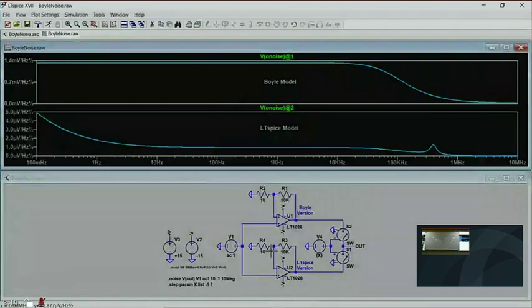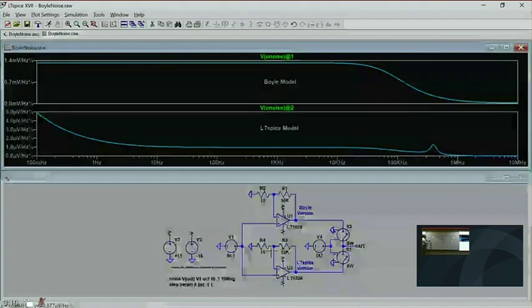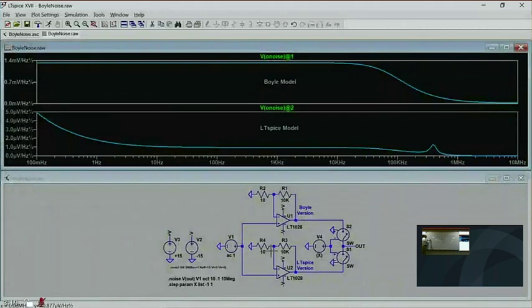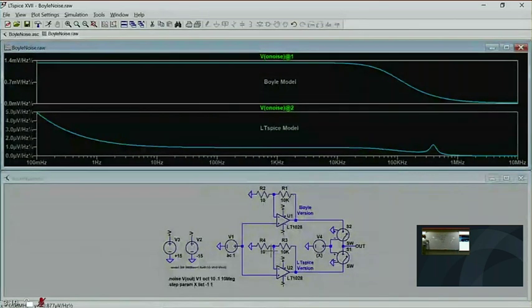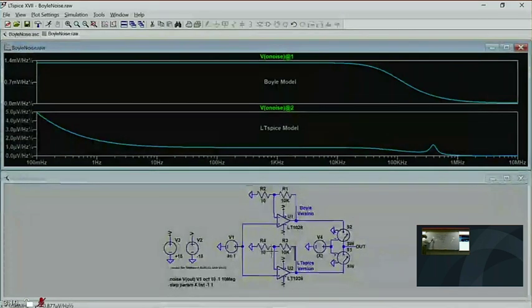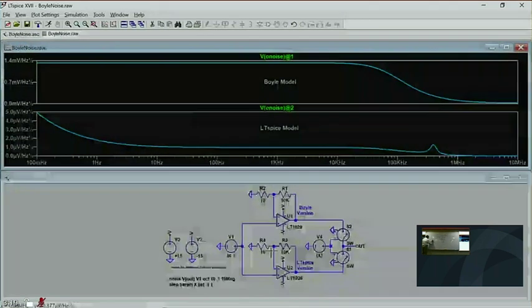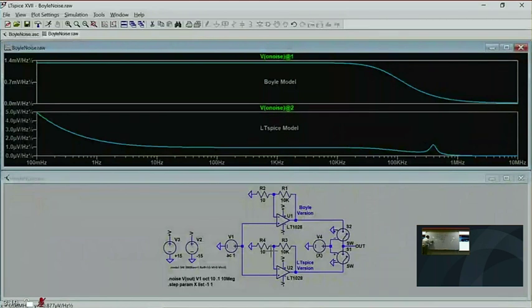Say that's the differential input pair of a JFET input op-amp. Well, if the noise on this current source is coupled to the inputs, say capacitively, that makes a common mode current going out the inputs, which will be read out to a voltage by the impedances seen on those inputs.